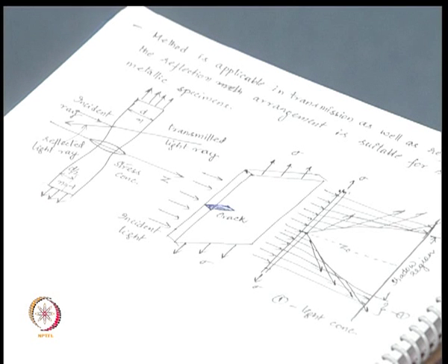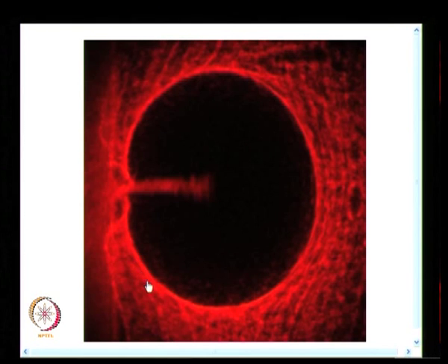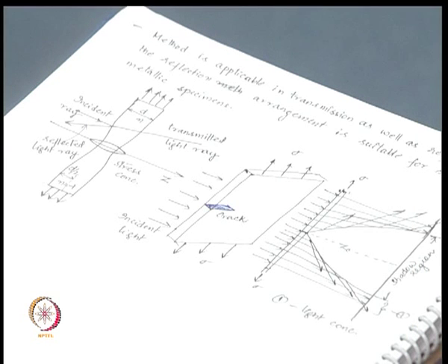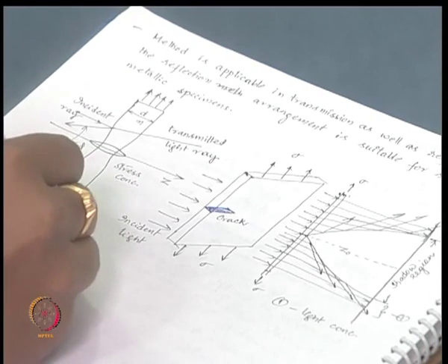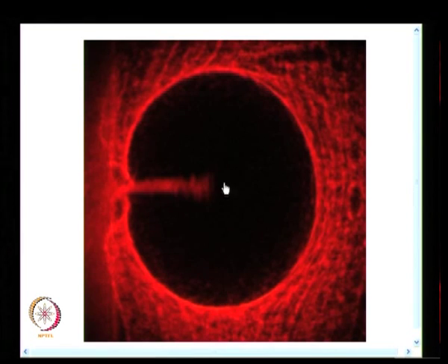The silver line is the caustic. In actual experimentation, you just measure this diameter, and then you have an equation which helps you find the parameter associated with the problem. In this case, you find the stress intensity factor by measuring the diameter.